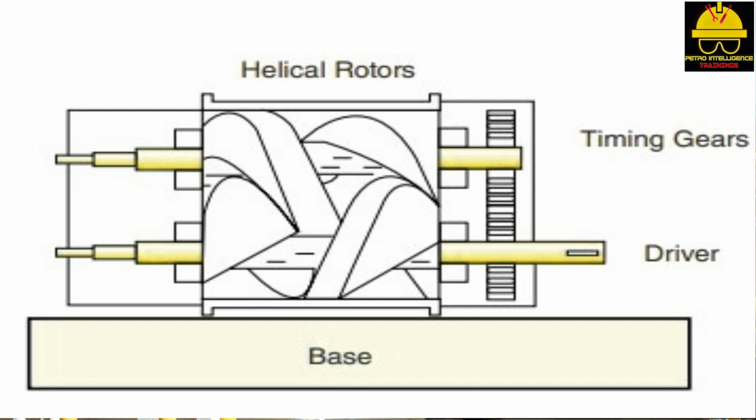The moving elements of the rotary screw compressor do not touch each other or the inner wall. A set of timing gears allows the power rotor to turn the alternate rotor. Because of this design, the rotating elements do not require lubrication, making them a perfect choice for dry gas service. Because of the small tolerances that exist between the moving elements, some internal slip occurs during operation.